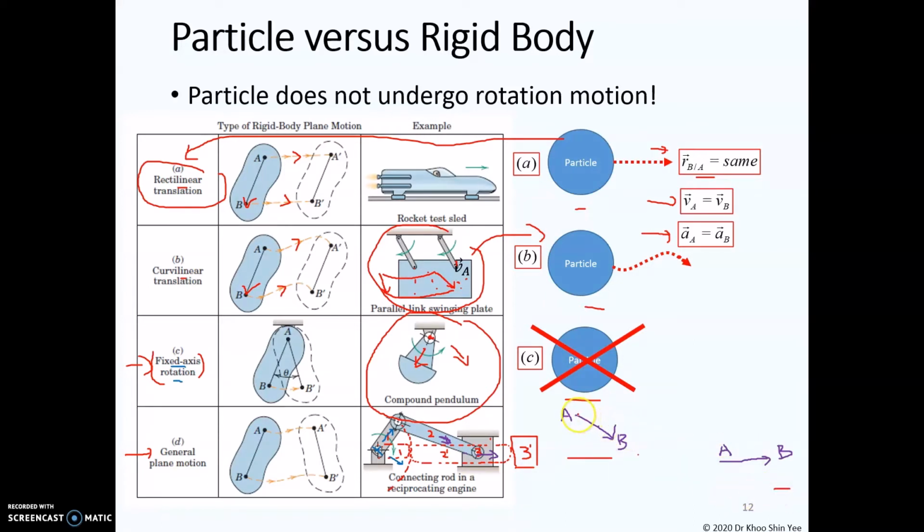You can see that point A here is doing translation. Then you move the relative vector to this position. To reach the final motion, point B here rotates with respect to A, and therefore you obtain the final position. Since the relative displacement of B with respect to A is doing the translation plus the rotation, in this case we have the general plane motion for rod 2.